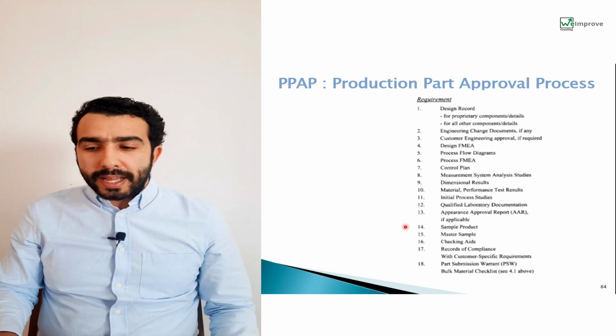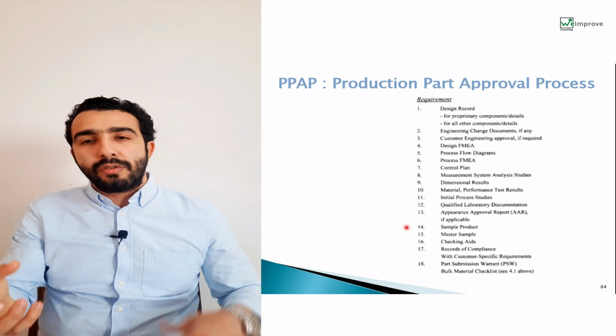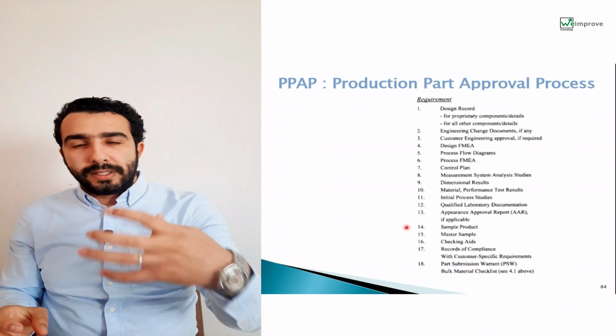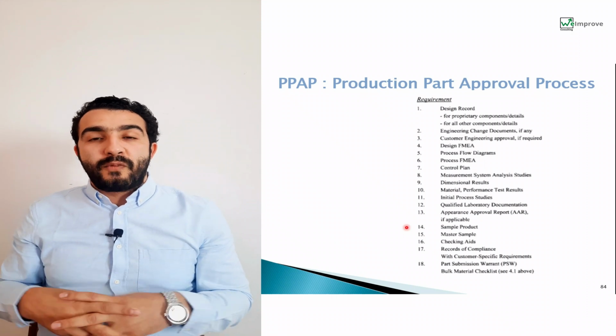The 14th is the sample product. As I told you, whenever you are sending the PPAP package documents, you also have to send the sample products to your customer. Firstly, to allow your customer to make some functional tests.